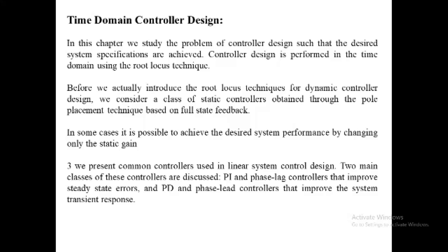It is shown that rate feedback control increases the damping ratio of a second order system while keeping the natural frequency unchanged, so that both the maximum percent overshoot and the settling time are reduced. Actually, controller design in the time domain was studied in the previous section, but the design algorithms are outlined for several types of controllers introduced in the section above.